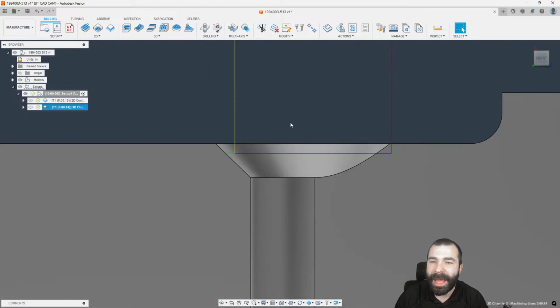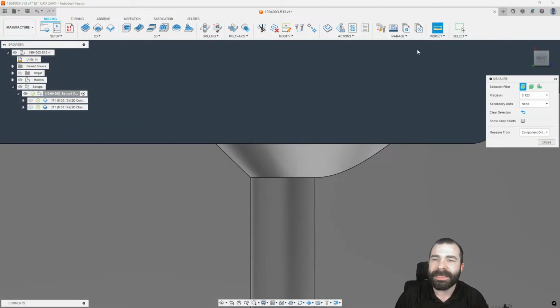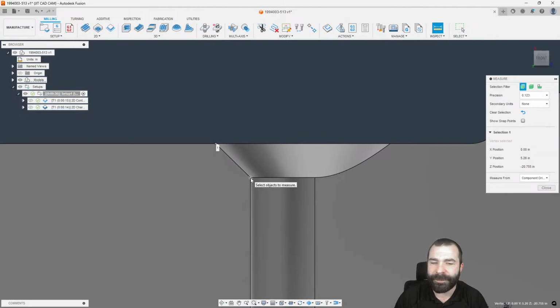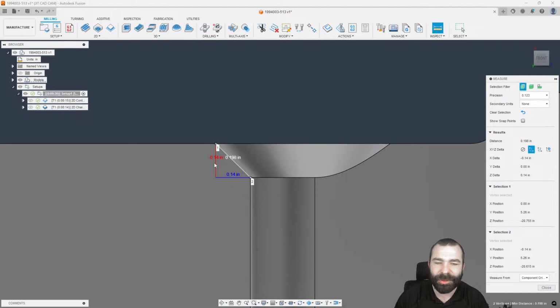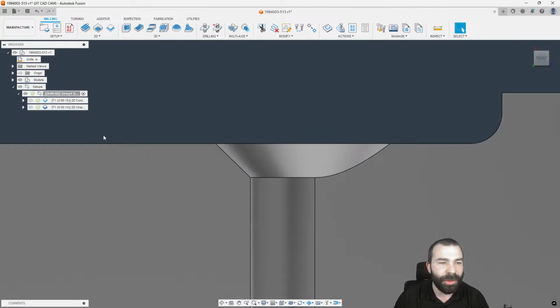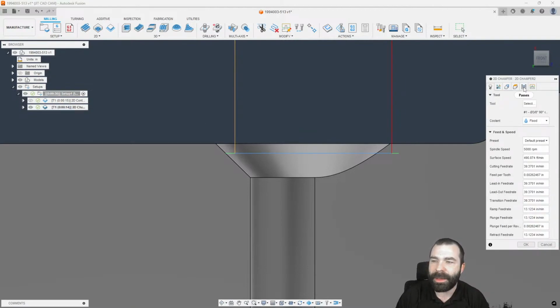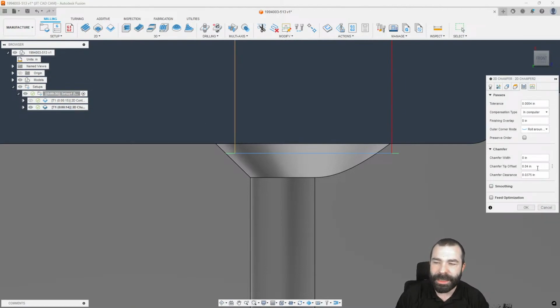So what I would have to accommodate for is how far off do I want to offset that tip? And in this case, if I do setting number 2, I need to add at least 140 to that. So if I wanted to go back into that tool path, now I'm going to keep 40, and then I'm going to simply say plus another 140. And what that is going to do is, one, we're going to have to remove that equal sign.